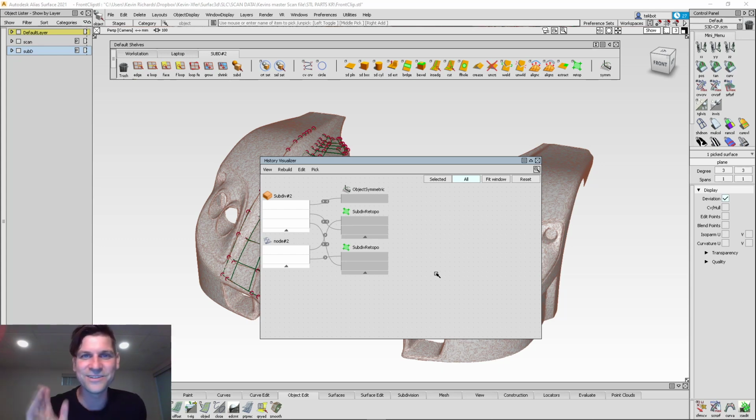Here's one little thing you can do. Take a square, right? You've got 4 curves that define your patch. One of those curves, create a new one, right? Whatever, new shape, new CV numbers, and come in here, and on your square, you can reconnect 4 new curves to the existing square, and it will rebuild it based off those curves. Like, that's awesome. So many times I want to keep the same surface. Maybe I have things aligned to it, but I want to change the underlying curves or swap them out, and you can't do that. We're now here.